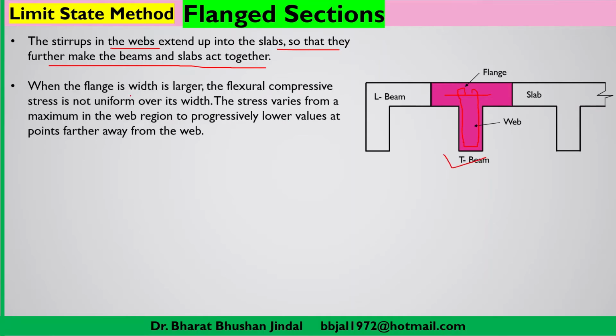Now, when the flange width is larger, this being the width of the flange, the flexural compressive stress is not uniform over its width. The stress varies from a maximum value in the web region to progressively lower values at points farther away from the web.